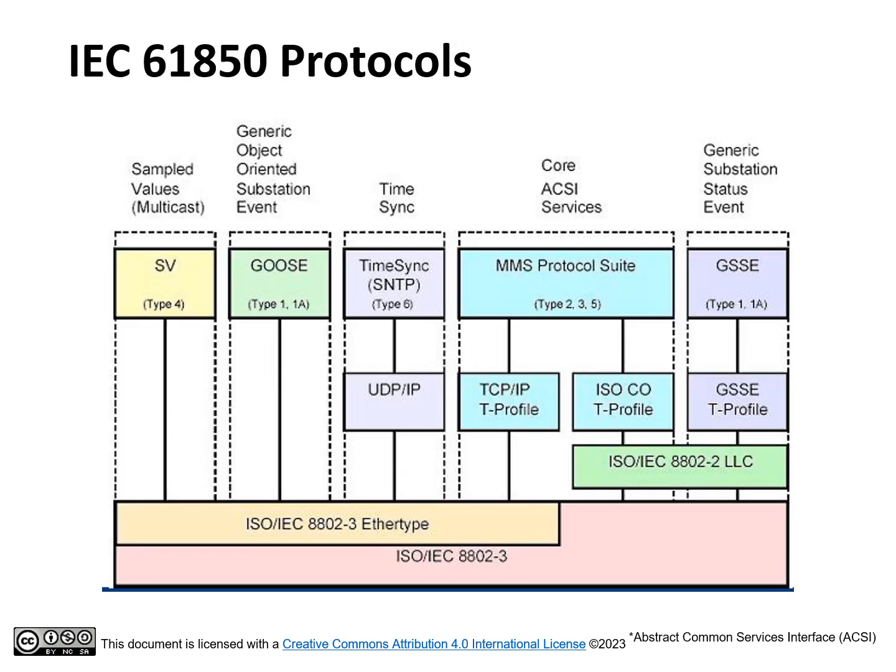This figure shows the communication protocols utilized by the IEC 61850 standard. The SMV and GOOSE are Ethernet Layer 2 multicast protocols. Layer 2 protocols provide data delivery with minimum delay, but cannot be routed. Layer 2 protocols are used in the local LAN inside the DER power plant or substation to deliver time-sensitive signals and control.